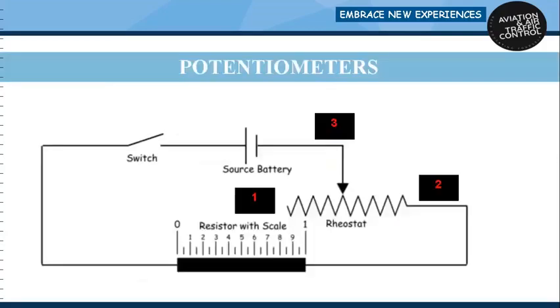Potentiometer. The potentiometer is considered a 3-terminal device. As shown, terminals 1 and 2 have the entire value of the potentiometer resistance between them. Terminal 3 is the wiper or moving contact. Through this moving contact, the resistance between terminals 1 and 2 can be varied. The potentiometer is used to vary the voltage in a circuit. A typical use of a potentiometer can be found in the volume controls on an audio panel and input devices for flight data recorders in aircraft.